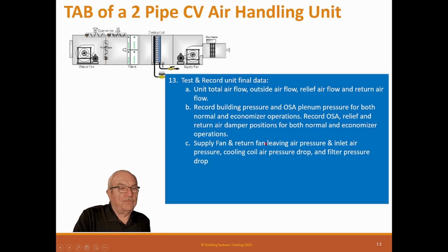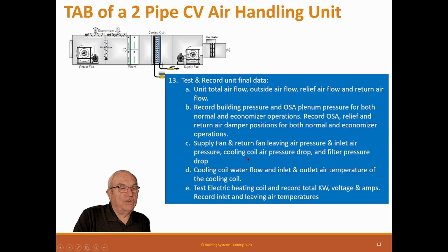Supply fan and return fan, leaving air pressure and inlet pressure. Cooling coil air pressure drops, filter pressure drops. Cooling coil water flow and inlet outlet temperature of the cooling coil. Test the electric heating coil and make sure it works and record the kW, voltage and amps.